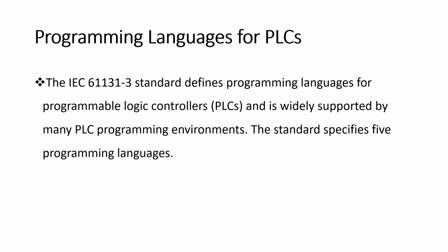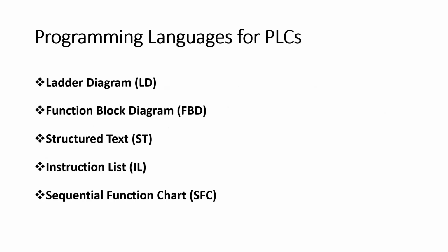The standard specifies five programming languages: ladder logic, function block diagram, structured text, instruction list, and sequential function chart. All of these are applicable depending on how easy it is for you to program the logic, and you will be able to run the PLC with any of these programming languages.